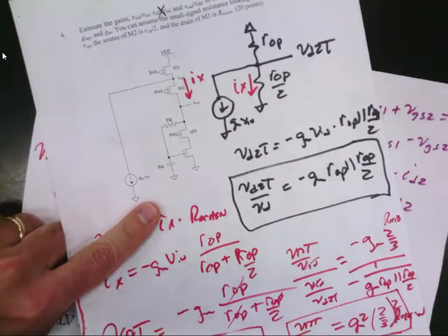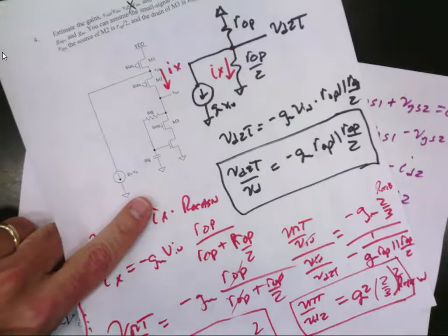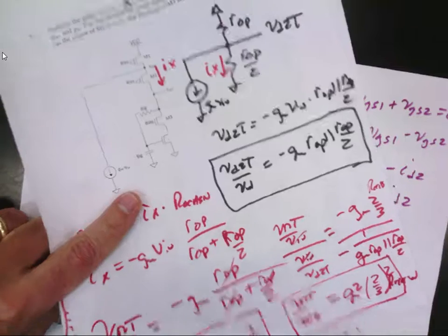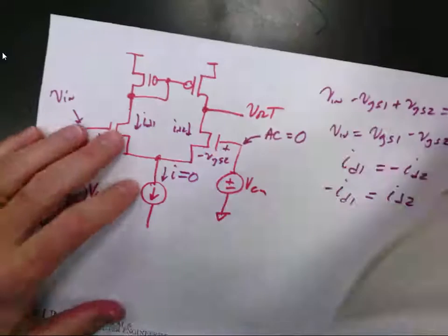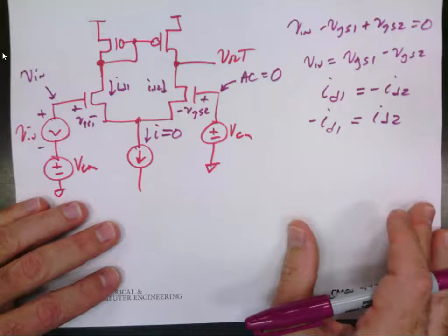That's why we talk about it all the time. The resistance looking into this node is this. You replace that node and all the circuitry that follows with a resistor to ground. Okay? Just like that regulated drain cascode. You got an op amp and you got a cascode structure and all that. That's why we talk about this, because it simplifies life.